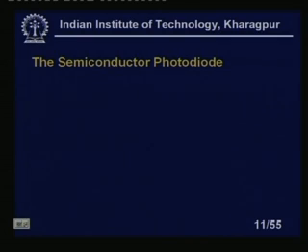Now, semiconductor photodiode. Now we have talked only about the photoresistors, which we also call light dependent resistors, but more applications in instrumentation you will find in the semiconductor photodiode. Photodiode and phototransistor are almost the same. In phototransistors, I will get some amplification, but the time constant is large, whereas in the case of photodiode, current is small, but the time constant is small.